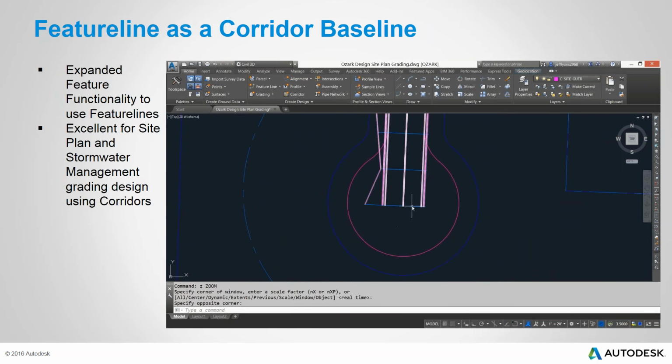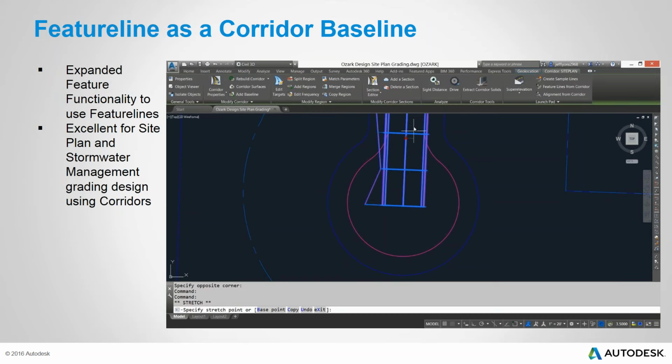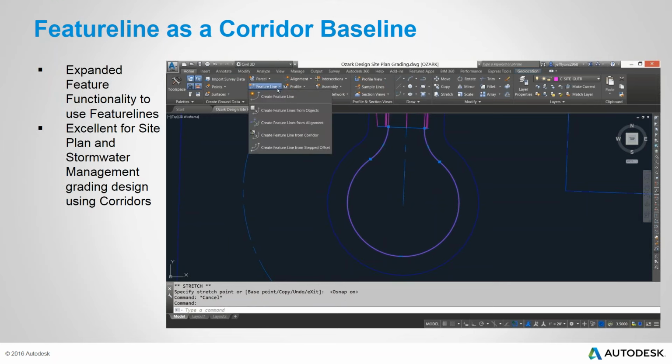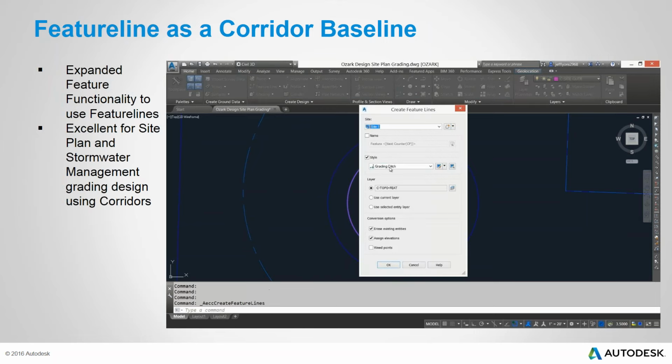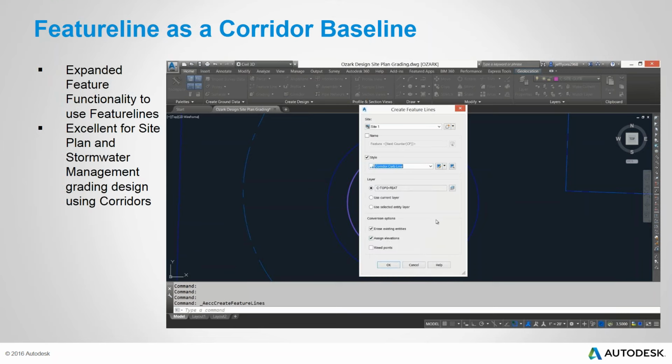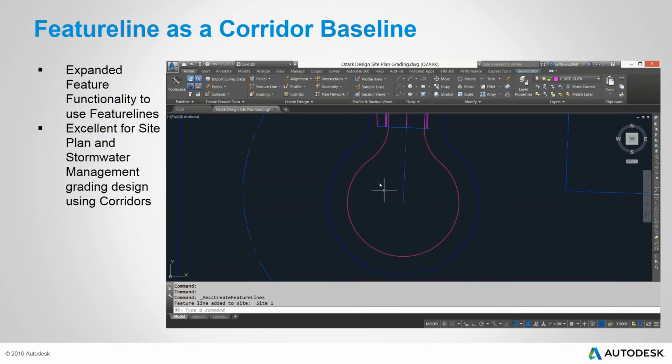For our third baseline, let's go and apply a curb to crown type assembly. So we can run the assembly along the curb line and target the center line of the road. Again, all create alignments with profiles for all of these baselines. So this will be valuable for anyone designing in urban areas or with lots of intersections.